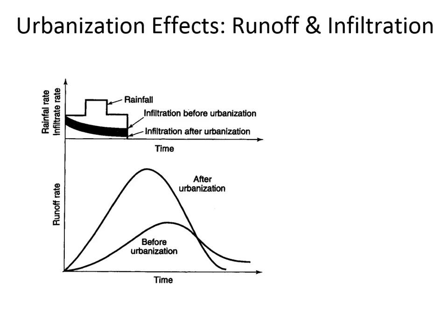It's a graph of water, hydrograph, time on the x-axis, and the runoff rate from a watershed, any kind of catchment. So you could have a hydrograph from a parking lot. You know, this parking lot that's right here next to the building, you could measure a hydrograph from that. A hydrograph could be coming off of a very large watershed, like the stream gauge at the New River Gorge Bridge. That could be used to generate a hydrograph that shows over time what flow rate is passing by that stream gauge.